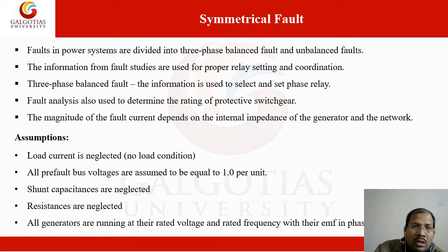Before proceeding to the symmetrical faults, there are certain assumptions. Here the load currents are considered negligible. There is no load condition, so during the faults we are not going to consider any load conditions. All pre-fault bus voltages are assumed to be equal to 1 per unit. At t equal to 0 a fault occurs, so we consider t equal to 0 minus, just before the fault.